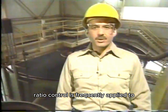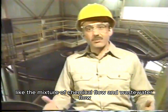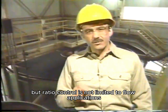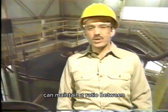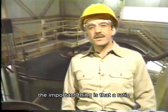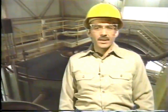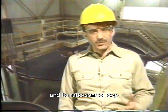Ratio control is frequently applied to processes involving flow mixtures, like the mixture of chemical flow and wastewater flow in this water clarifying process. But ratio control is not limited to flow applications. For example, ratio control can maintain a ratio between two temperature measurements, or two pressures, or two levels. The important thing is that a ratio is maintained between two or more variables. Let's take a closer look at this water clarifying process and its ratio control loop.